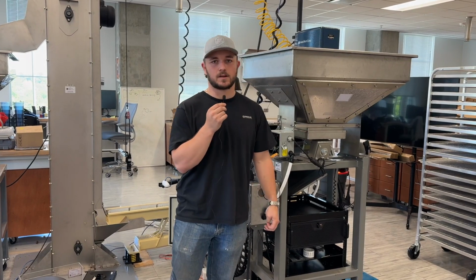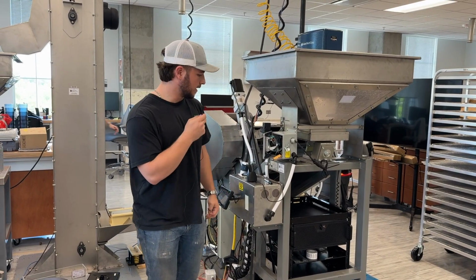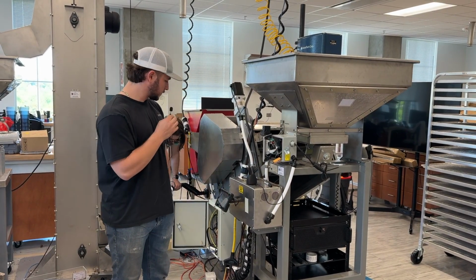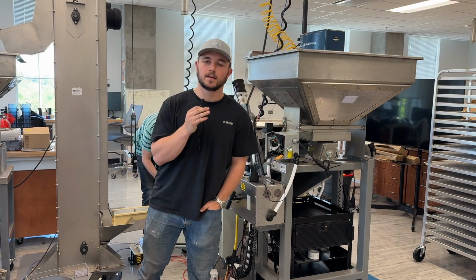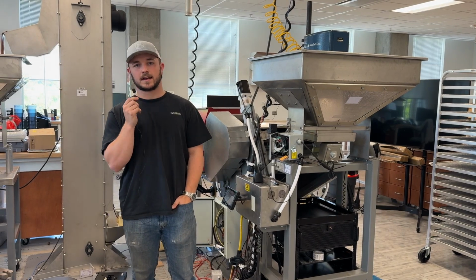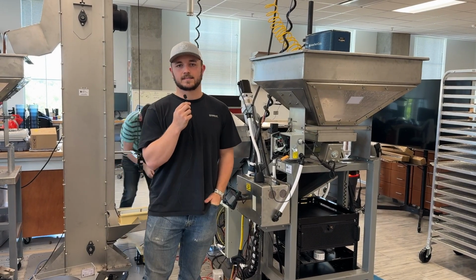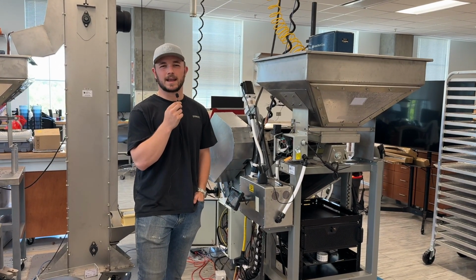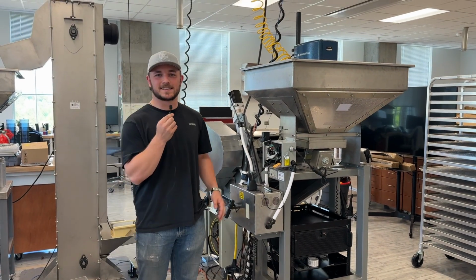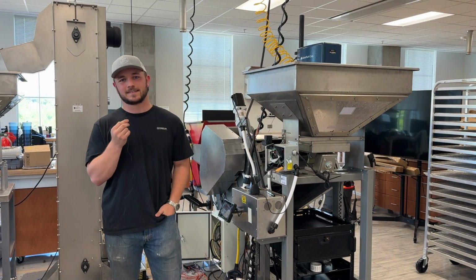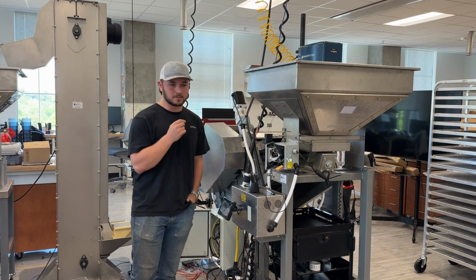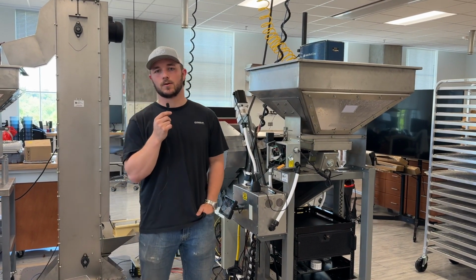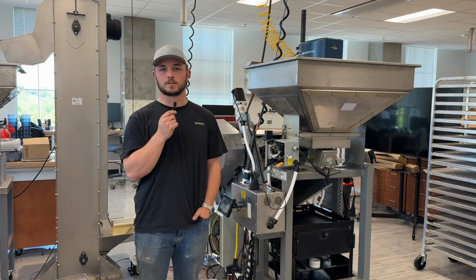We've optimized our control system such that at our lowest throughput of 13 pecans per second, we're seeing a steady state error of less than 0.8%. And at the worst case scenario of 38 pecans a second, we're seeing 0.5% steady state error. That is much lower than the acceptable threshold of 5% steady state error, which we're very happy with.